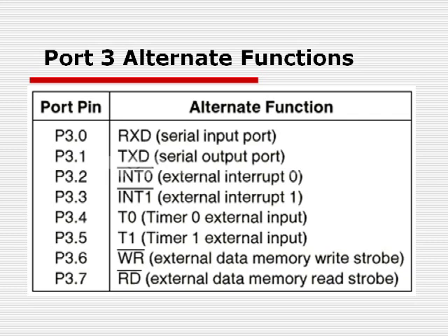If I want to use any of these port pins as output, then those port registers should be initialized with zeros. If I want to use any of these port pins as input, then those registers should be initialized with logic 1s. And the same registers hold the data when we want to transmit to or receive from the external peripherals.